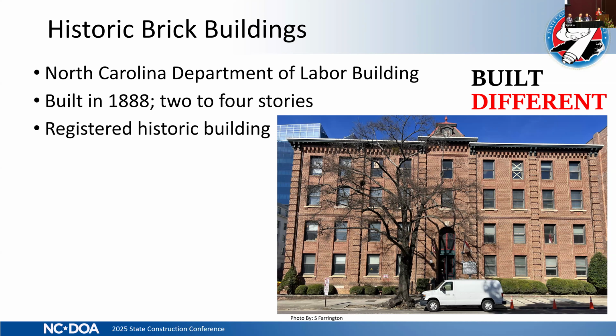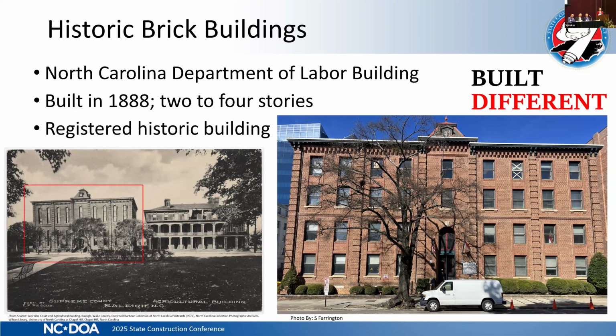Some of you may think that it was a 2-story building that they then built 2 more stories directly on top of. But if you actually look at the exterior design features of this building, go ahead, look, check it out. You may start to notice that the design features are actually pretty consistent from ground level to the roof. You may notice that the bricks between the windows are a little bit darker than the rest of the brick. They renovated this building to go from 2 20-foot stories to 4 10-foot stories. Each of those window openings used to be the full height of the original stories. Keep this in mind as we go through this presentation.